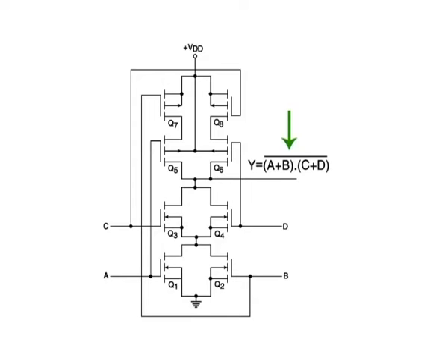It is very simple to draw the internal schematic of an AND-OR-invert or OR-AND-invert gate. The circuit has two parts, that is the N-channel MOSFET part of the circuit and the P-channel part of the circuit. The two parallel arrangements are connected in series to achieve an ANDing operation.